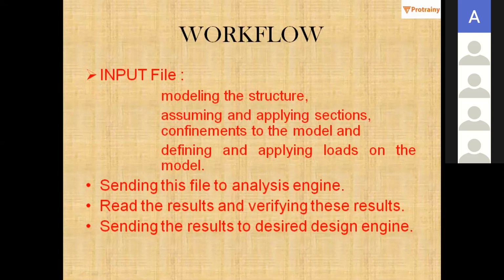After completion of this input file, when a user is satisfied that the model he or she creates is as close as possible to the real thing, you will be sending this file to the analysis engine. Then after getting results from this analysis, you are going to verify these results. This is one of the most important aspects of STAAD, and that's where your experience with manual methods comes in handy.